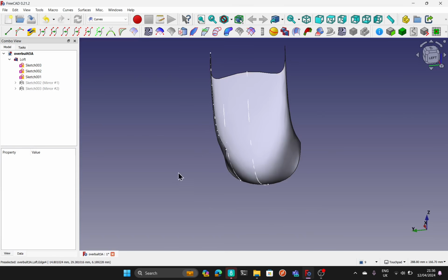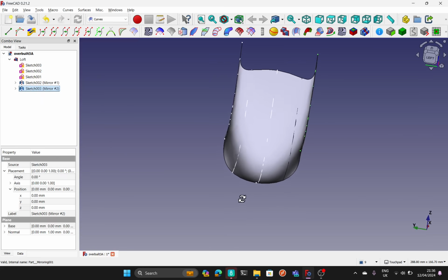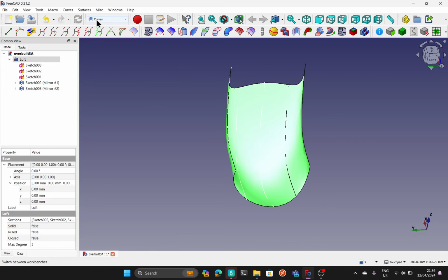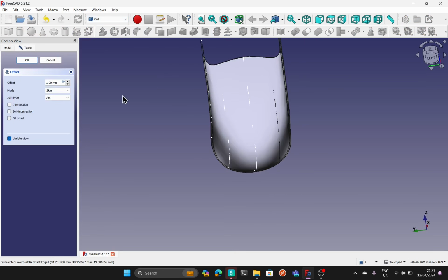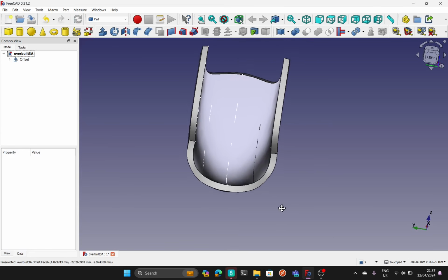You notice that I've used mirrors. So I've got a mirror of the sketch. Now there's a reason why I haven't mirrored the loft itself. So created 3 B-spline curves and then created the loft and offset the loft and mirrored it, because when we offset this, we'll see a different result. So if we offset this and put this up to say 5 and fill the offset, you see we get a nice curvature going across there.